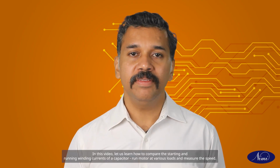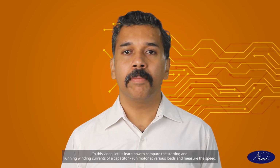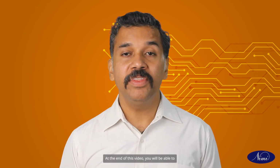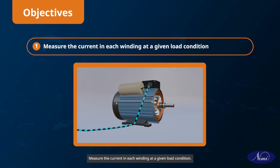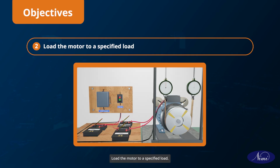Hello everyone. In this video, let us learn how to compare the starting and running winding currents of a capacitor run motor at various loads and measure the speed. At the end of this video, you will be able to measure the current in each winding at a given load condition. Load the motor to a specified load.